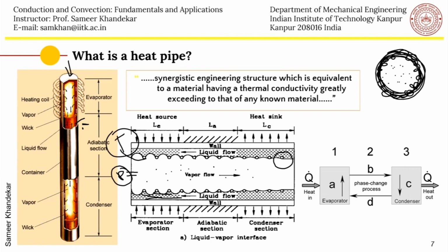This single component two-phase mixed working fluid is in equilibrium. It comes to equilibrium eventually. Initially when we were filling, it was in non-equilibrium because there was vacuum inside, but eventually if you give enough time, it will come to an equilibrium position. Now the heat pipe is ready to operate.